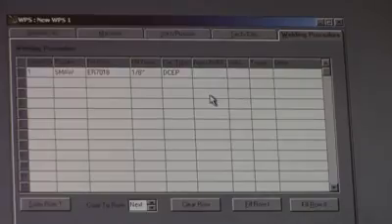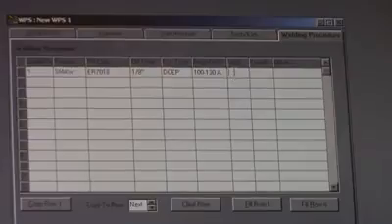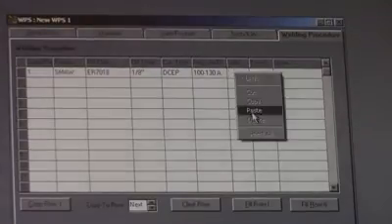On a WPS, you need to give a range because not everybody's going to have the same kind of machine. Some welders like to run it hot, some like to weld a little bit cold. As long as it's not dangerous and it's within the range that you give, it's good to go. With 1/8 inch 7018, I would say anywhere from 100 amps to 130 would be acceptable, but 130 is pretty hot for going up. Volts, because this isn't MIG, we're going to go NA.